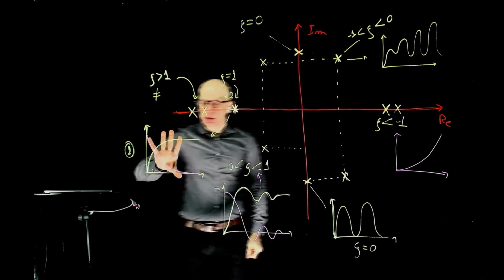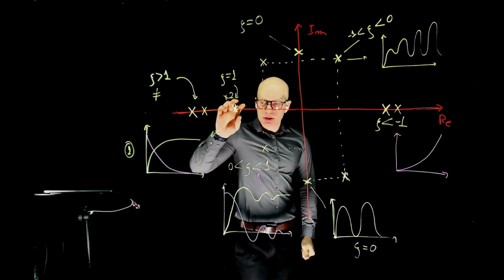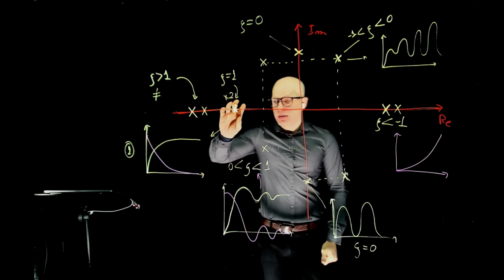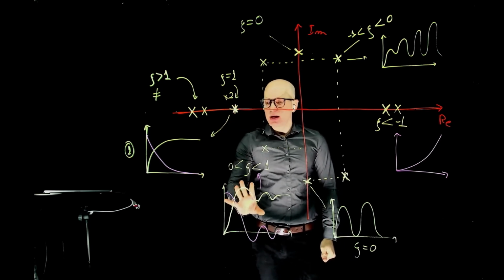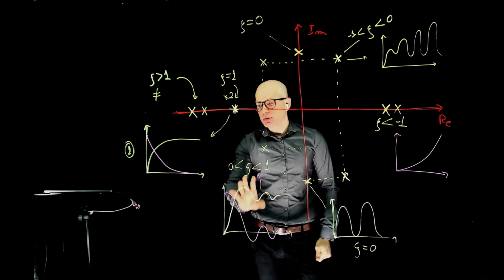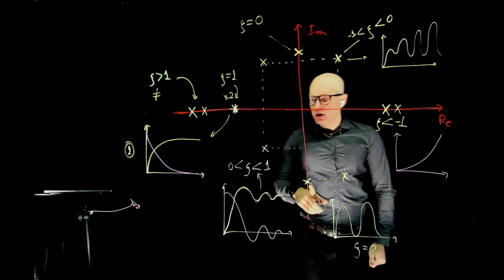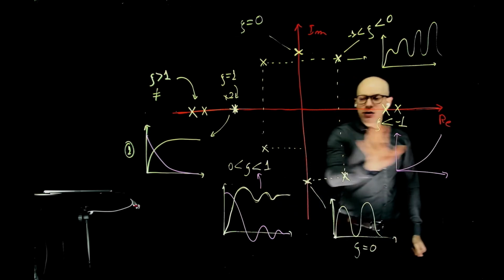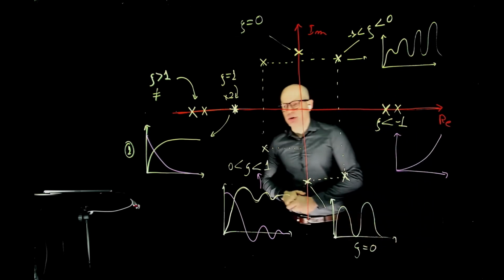So to summarize, overdamped, lots of damping. Critically damped is still lots of damping, but we are to the point where the system will become underdamped. Underdamped, not enough system damping, so we start to see oscillations. Undamped system, no damping at all, only oscillations. And then anything that lies on this side of the S-plane is unstable and has no interest for us.